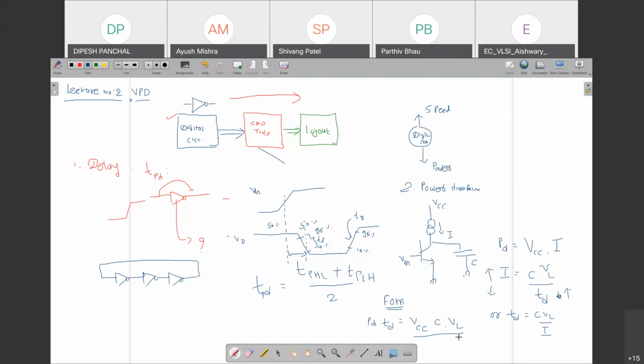You have to worry about it, not independent current or independent delay. If you worry about independent current and delay, there is always a trade-off. Current is high because of a change in this R or something like that. To worry about speed. But most IC design companies specify the power delay product. Power delay product is a constant term, independent of current variations.